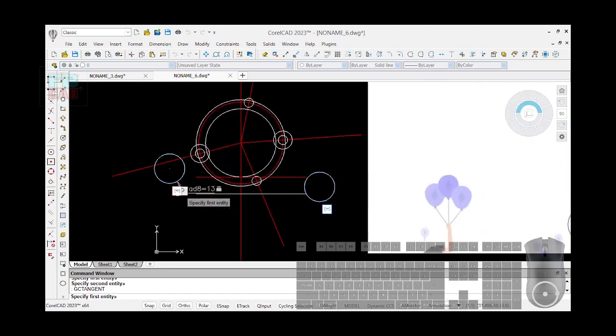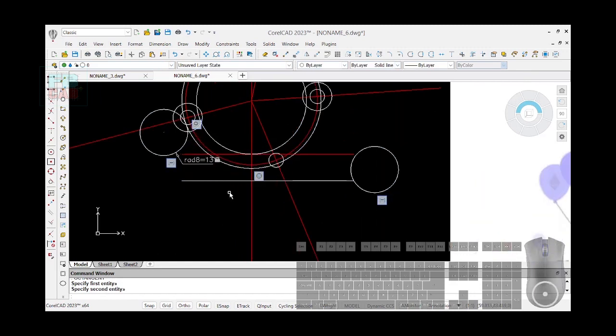So that's what we're going to do. We pick this outer circle and this and make them tangent. Now this line is going to be fixed, geometric constraint fixed. This horizontal line ought to be fixed. Okay, so geometric constraint tangent, we are taking enter, taking this and this needs to be a tangent.